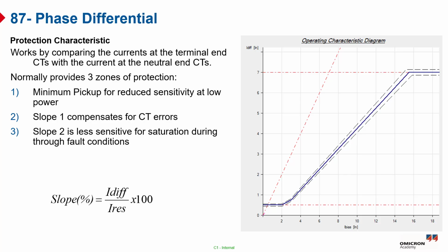So the differential protection characteristic is defined by the differential current Idiff and the stabilizing or bias current Ibias, which accounts for CT errors and saturation. The operating characteristic must always exceed the summation of expected errors to reliably distinguish between blocking and tripping conditions, using a low slope to improve sensitivity to evolving insulation failures and detecting small leakage currents before they escalate. But the slope must balance sensitivity and security to avoid false trips.